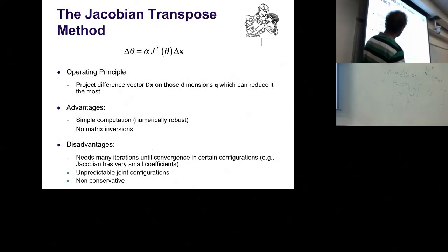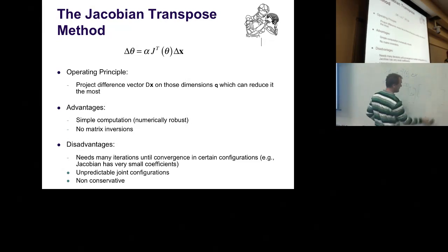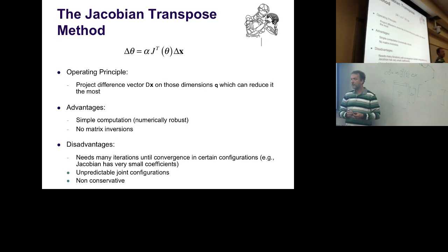the math here. This Jacobian transpose is a method which gets you at every step you take, every delta, closer to the goal, but in a weird way. What actually is going to happen from a robot point of view, this picture, and here's your target, you usually move in a way which looks like this, some bizarre curved path. If you follow that, you will get to the goal, since the Jacobian transpose with this inner product always promises you that you will make some progress towards the goal, just not the directed path. So it's like, you want to go to downtown and you go through, I don't know, Griffith Park. So it's a little bit of a detour. But you will get there.